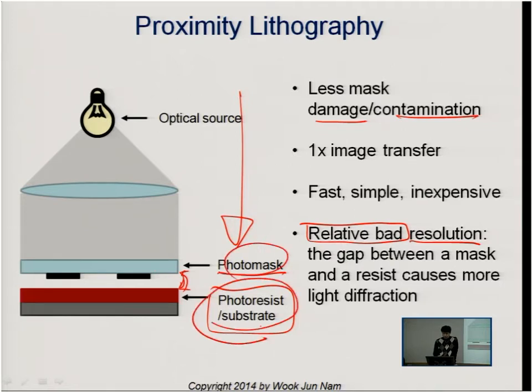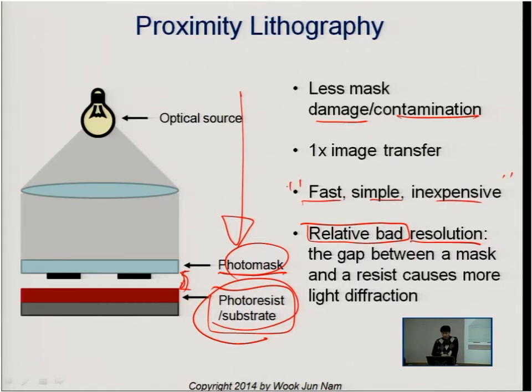It also uses the same size of photomask and substrate, so it only needs one exposure, which is the same advantage contact lithography has. And both contact lithography and proximity lithography do not use any lenses, so the pattern transfer ratio is 1:1. In other words, if you have a 1 micrometer feature size on your photomask, the transferred pattern is also 1 micrometer.